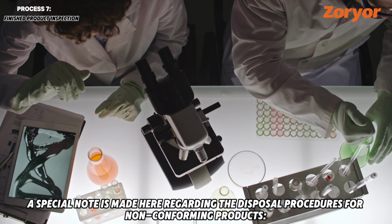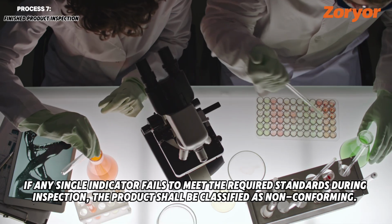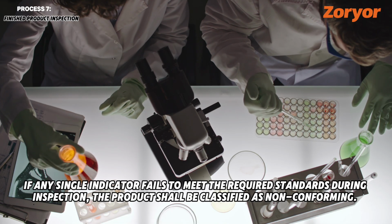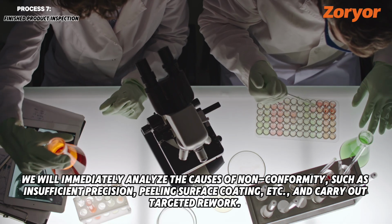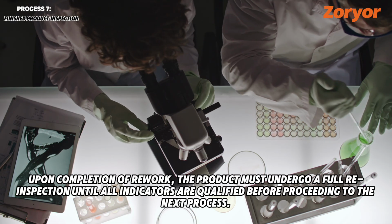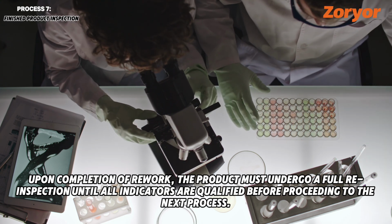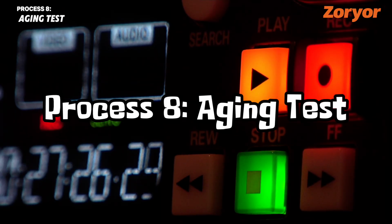A special note is made here regarding the disposal procedures for non-conforming products. If any single indicator fails to meet the required standards during inspection, the product shall be classified as non-conforming. We will immediately analyze the causes of non-conformity, such as insufficient precision, peeling surface coating, etc., and carry out targeted rework. Upon completion of rework, the product must undergo a full re-inspection until all indicators are qualified before proceeding to the next process. Process 8.